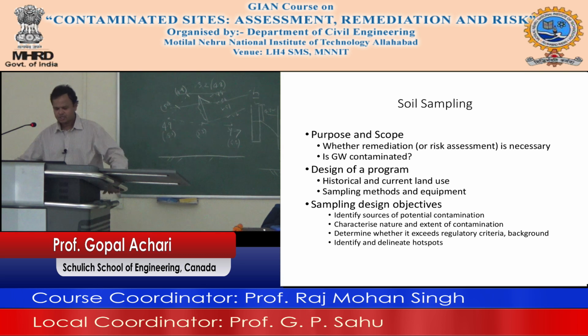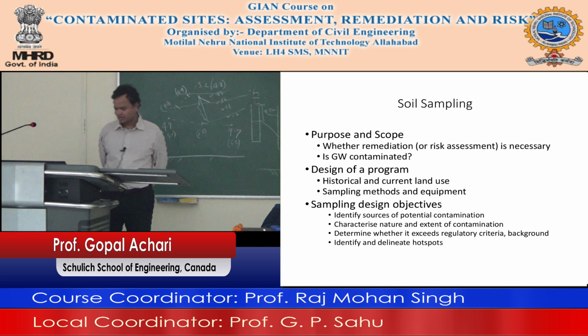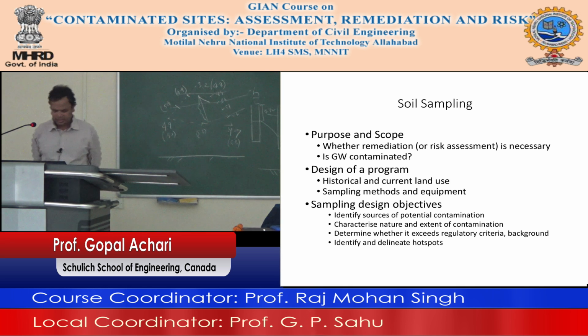Sorry. So the soil sampling purpose and scope. Whether remediation is necessary. Is groundwater contaminated? The design of a program, the historical and current land use, sampling methods and equipment all have to be recorded or thought through. Sampling design objectives: identify sources of potential contamination, characterize nature and extent of contamination, determine whether it exceeds criteria, and background.